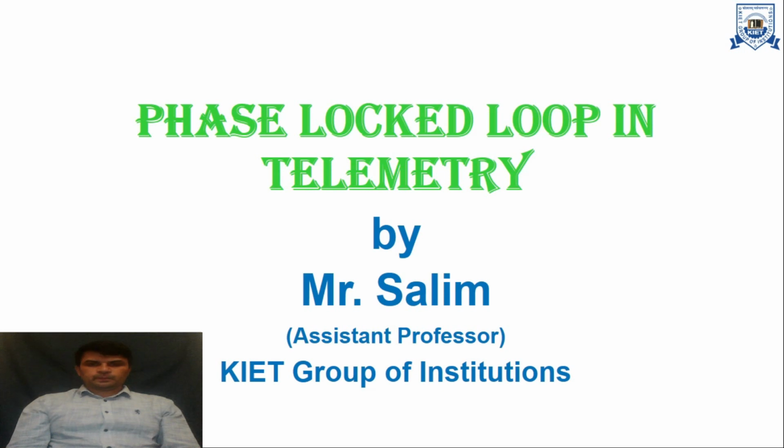A phase locked loop, also called phase lock loop, is a control system that generates an output signal whose phase is related to the phase of an input signal. There are several different types. The simplest is an electronic circuit consisting of a variable frequency oscillator, a phase detector, and a feedback loop.